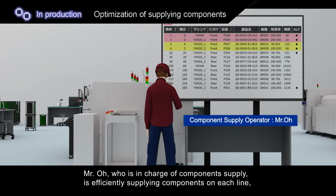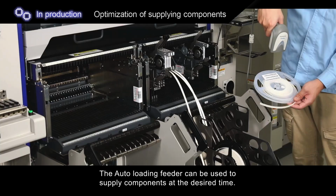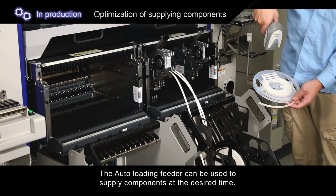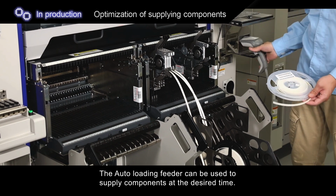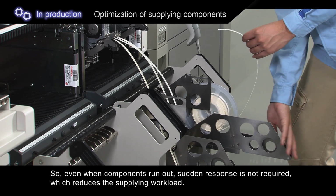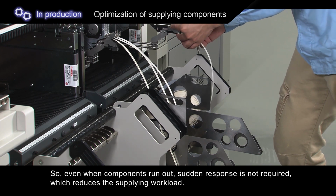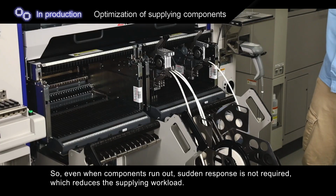Mr. O, who is in charge of component supply, is efficiently supplying components on each line, checking the number of remaining components on the large screen and notifications on a mobile device. The auto-loading feeder can be used to supply components at the desired time. So, even when components run out, sudden response is not required, which reduces the supplying workload.